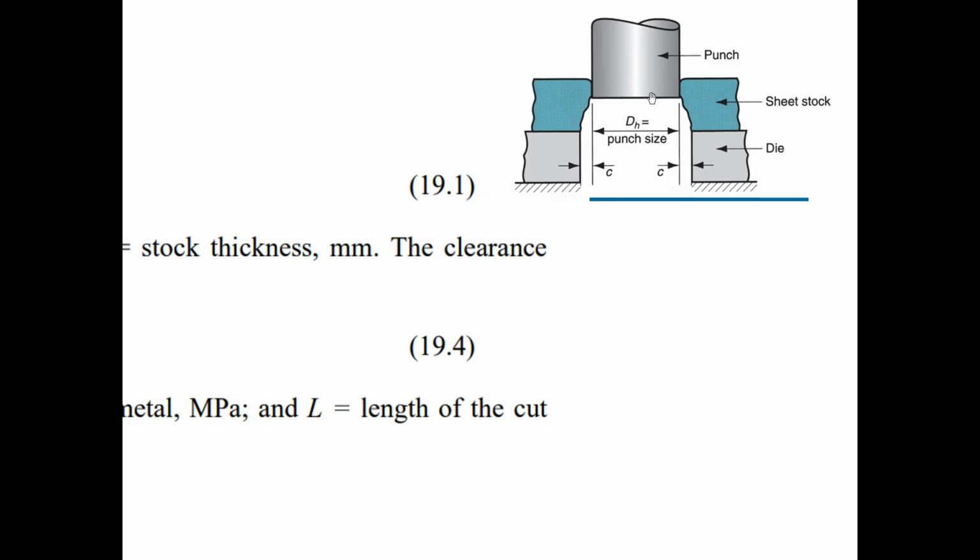the two. In punching operation, when we are just going to make a hole on the actual workpiece material, it is the size of the punch that is of importance, and that is the one that will be left on the workpiece. But if this is representing a blanking operation, then what is coming out of the die opening right here is the desired part. So it is the size of the die opening that is deciding the size of the workpiece material. So we should be careful in applying the clearance to the punch or to the die as needed.